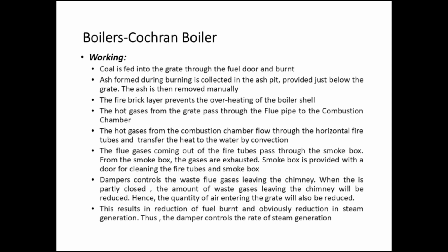The hot gases from the combustion chamber flow through the horizontal fire tubes and transfer the heat to the water by convection. The flue gases coming out of the fire tubes pass through the smoke box. From the smoke box, the gases are exhausted. The smoke box is provided with a door for cleaning the fire tubes and smoke box.